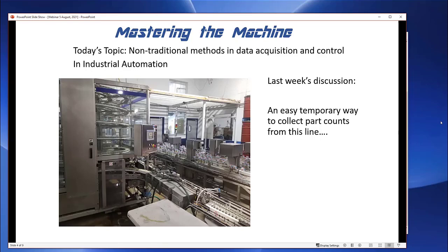So that's where, when we talked, you mentioned that everything was so high frequency, and of course, those devices are going to do their analysis over there somewhere. And then if you needed to do something with a PLC, they would possibly report to the PLC that, hey, you're nearing a failure point or something. But as far as the actual data, it's so many data points that it wouldn't be particularly useful to bring that into the PLC end of things. It would be much more, I suppose, on the computer end. And then you would report that, hey, you have an imminent failure on your bearing or something.